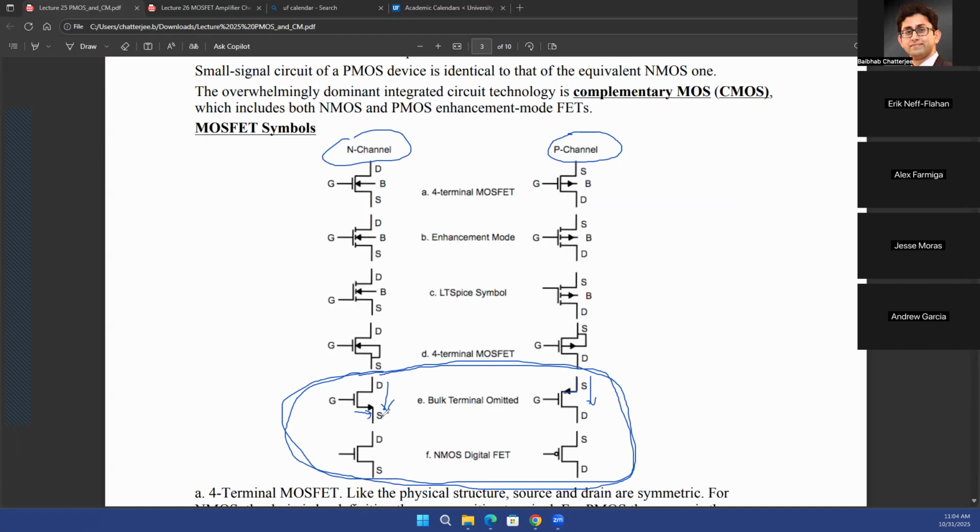In digital electronics, if you're sampling the value at specific time intervals, then your time is not continuous, time is discrete. You can also quantize the amplitude. You can have a 0, which is a low amplitude, and a 1, which is a high amplitude for the signal. Then you're quantizing or discretizing the amplitude as well. So both in terms of time and in terms of amplitude, digital is quantized, and it's much simpler, just in terms of the behavior of the MOSFET. But of course you can implement a lot of algorithms in digital. That's where the complexity comes in.